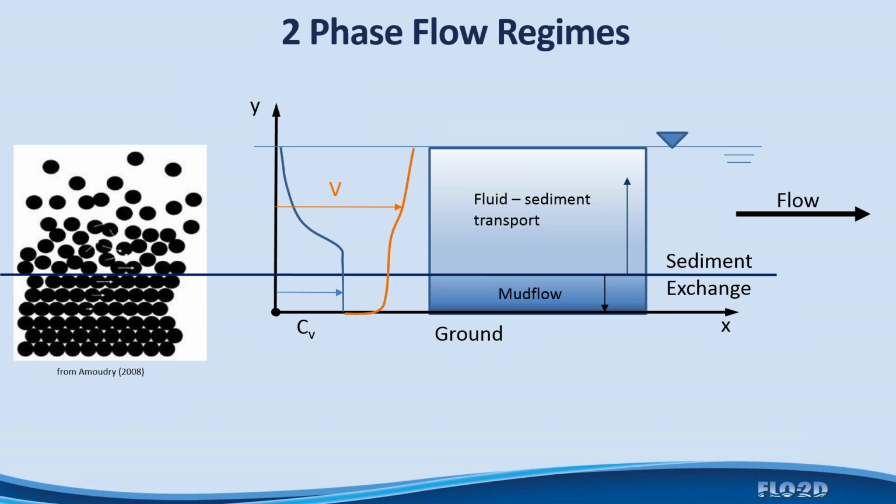Now, let's discuss the two-phase flow component here. What I'm not capable of doing, let me start that way, is that I'm not doing Lagrangian particle dynamics here. I'm not tracking individual sediment particles, computing the lift and drag on each particle component, getting a mixing zone and having the particles cross the mixing zone. I'm doing gross volume finite difference modeling of the fluid sediment transport on a cell basis, and then the mud flow, which would typically be under the fluid phase, separately, and then I'm exchanging between the two.